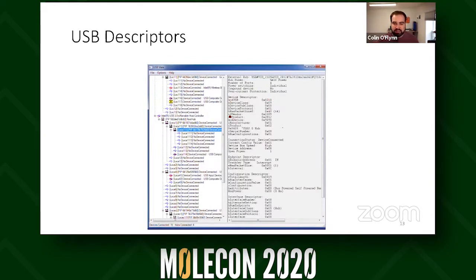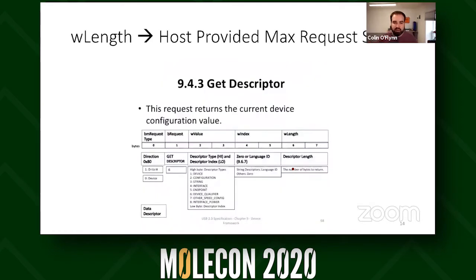So you can see there's stuff like vendor ID, product ID, but you also have strings, right? So there's a string that says, hey, this is a USB 2.0 hub. And you also have stuff like the endpoints, right? So this is how the device is going to talk to it and things like that. So we have a few different configuration blocks that are getting sent from the device up to the computer. And then the computer knows what you've plugged in, how to talk to it, what driver to load, anything like that.